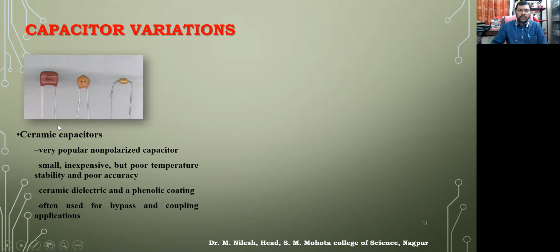So this is what I was talking about. This is a ceramic capacitor, which implies that the dielectric medium, or non-conducting medium, used between these two plates is ceramic, right? So where ceramic is used, these are called ceramic capacitors. We have a lot more ceramic capacitors over here. Whenever offline classes start, I'm going to show you all those ceramic capacitors and how to calculate their values, right? This doesn't have any polarity. These are very cheap with respect to electrolytic capacitors, and they are very sensitive to temperature, and these are some of the drawbacks.